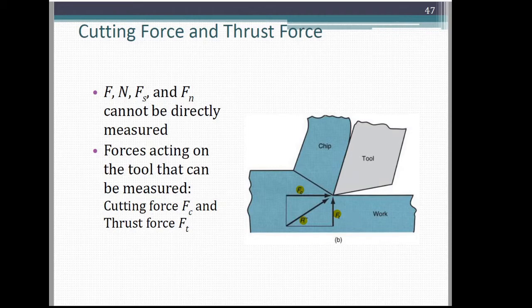How do you measure the magnitude of non-measurable forces F, N, Fs and Fn? For that, you can use the measurable forces Fc and Ft. If you are measuring the cutting force and the thrust force, with that you can calculate the magnitude of the non-measurable forces F, N, Fs and Fn. For this purpose, we use the merchant circle diagram.